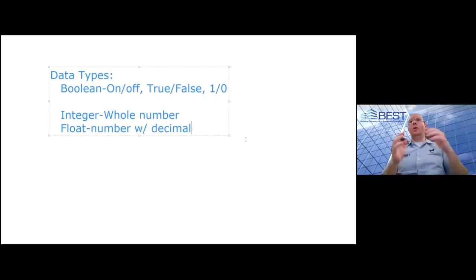For whatever reason, the system was counting seconds cumulatively, and eventually it got to so many seconds, and if you calculated it, it was 48 days and a certain number of hours. When it clicked over, it would actually overflow the stack. The data type for the object that was counting crashed because it couldn't add one more second into it. So that's the only time I've ever run into data overflow issues in a control system.